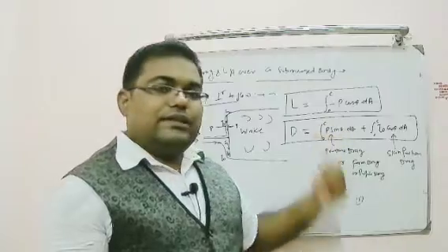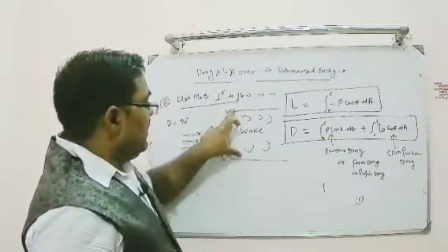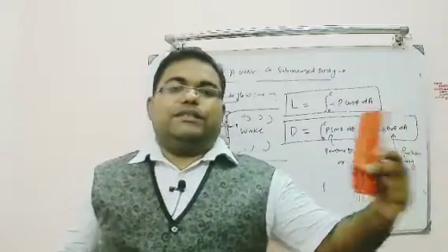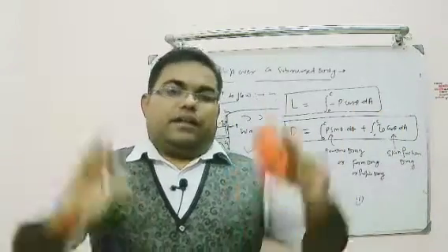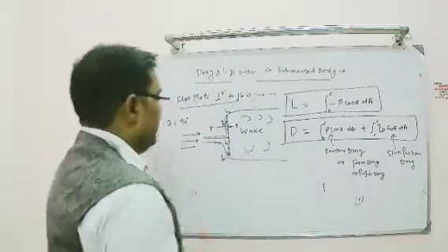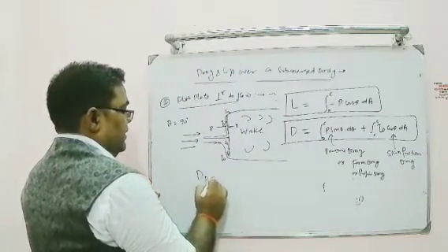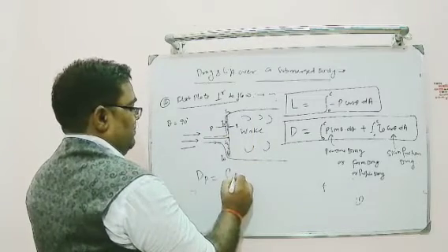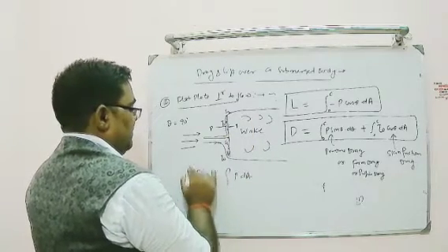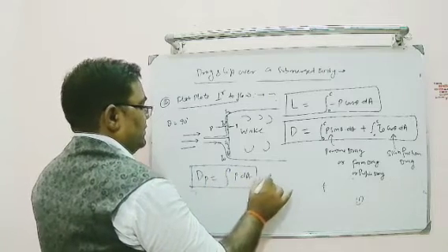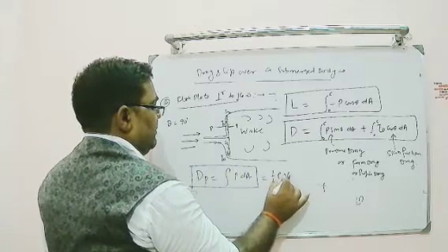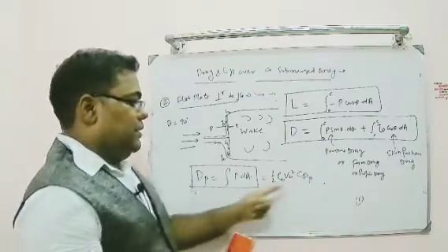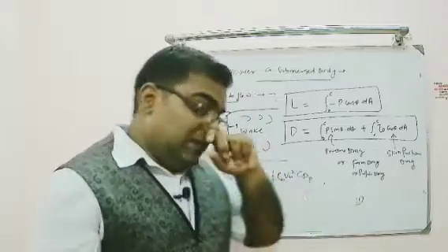This is the pressure drag, and if you look at it, the wake area is bigger. So if my flat plate is facing the flow at 90 degrees, it will generate a larger amount of drag, called pressure drag. So there will be pressure drag D_P, which is simply the integral of P dA over the area. This formula is similar: half rho infinity V infinity squared S times C_dP, where C_dP is the coefficient of pressure drag. Like that we can find it out.